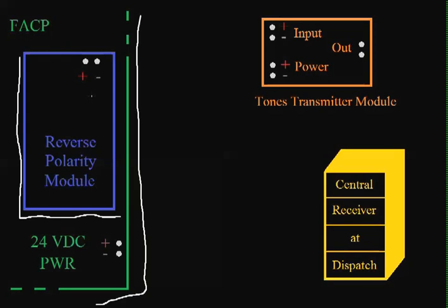So reverse polarity is a concept we introduced once before, and that's when we were describing horn circuits or NAC circuits. If you remember, on a NAC circuit, the standby voltage would be, let's say, a positive 24 volts, and when it goes into alarm, it reverses, or possibly vice versa. Maybe the standby, I think the way I presented it was the standby voltage would be a negative 24 volts, and when it went into alarm, it would switch. Well, this is a very similar concept.